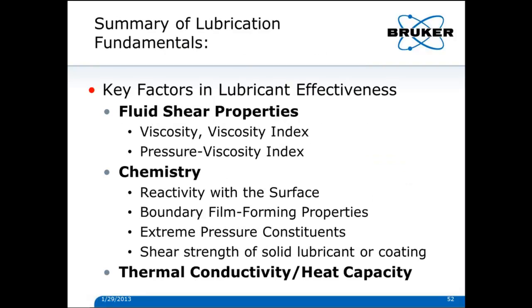If I could summarize now these lubrication fundamentals, we've got key factors of fluid shear properties, chemistry, and thermal conductivity or heat capacity. I didn't mention that too much, but we need to take the heat away from the sliding interface. So in the fluid properties, we've got the viscosity and viscosity index, or how it changes with shear rate. We also have the pressure viscosity index.